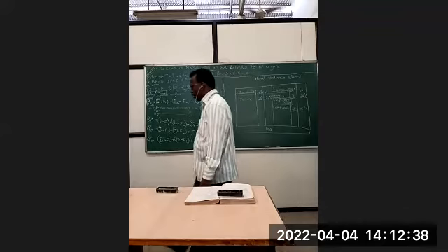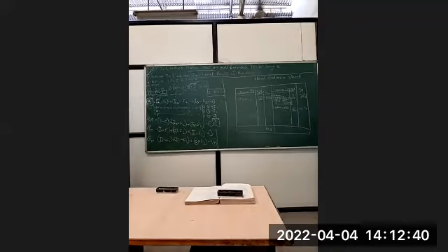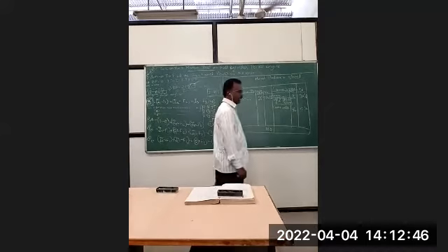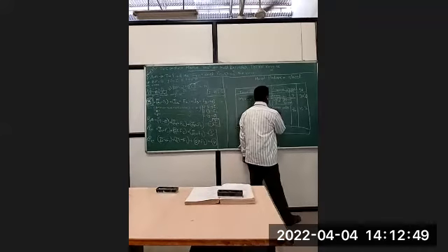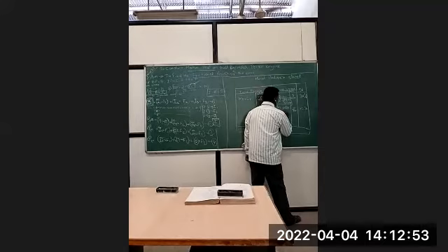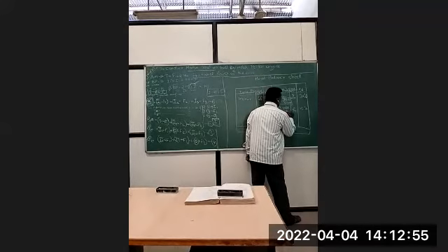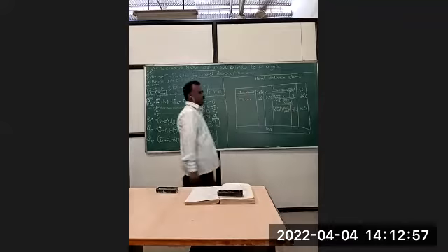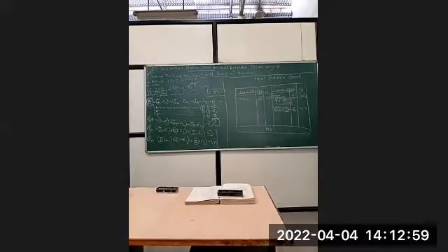We assume that whatever amount of heat is lost by the engine will be gained by the water which is circulated in the cooling system. So this Q, the amount of heat loss, we can calculate by m Cp delta T. So what is m? m is the mass flow rate of water.